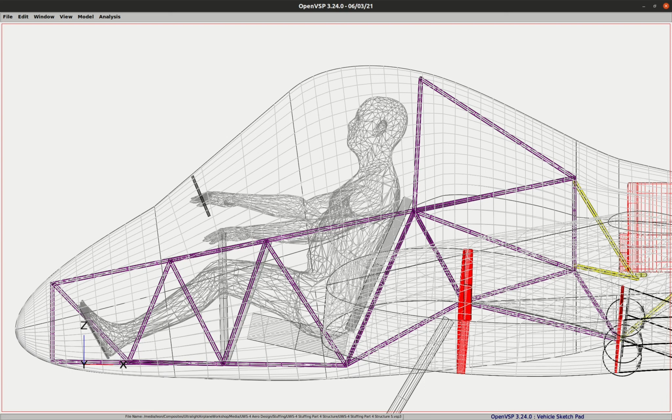Let me show that. So here's where we're going to have the hatch for the fuselage. There will be a hinge on one side and latches on the other so that this can flip up. So that's how you'll get in and out of the airplane. And I'm going to have a composite structure, or it could be aluminum, in here. So that will provide some more rollover protection. So now we have a line from here to here, which gives us a little bit better protection if we roll over. So this will be a Lexan windshield that you can see through, so it could crush in just a little bit, but we have much better rollover protection here.